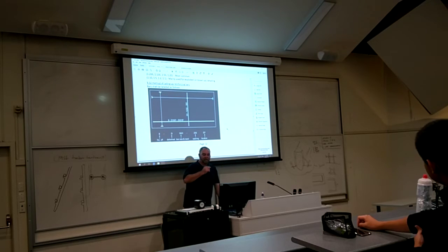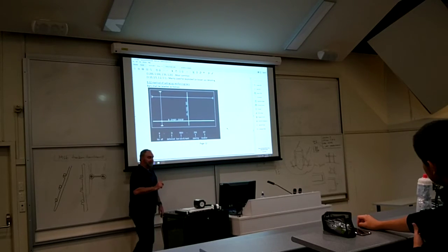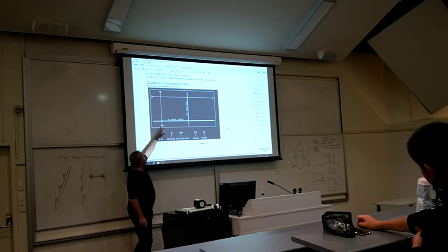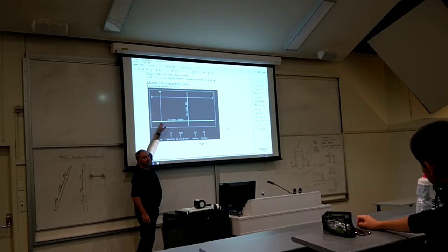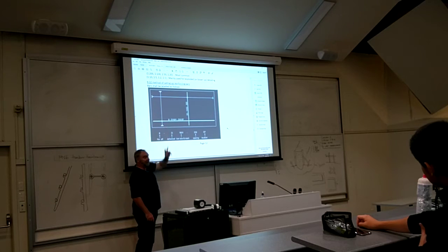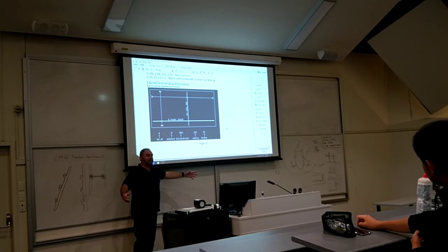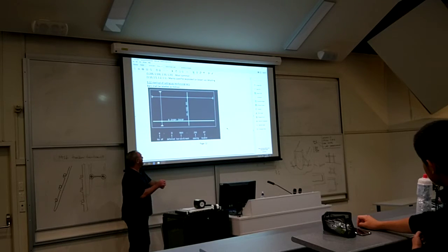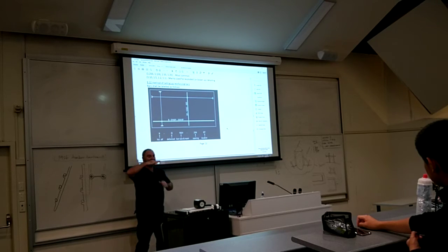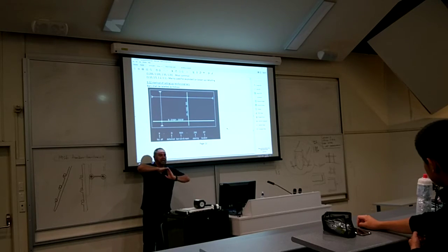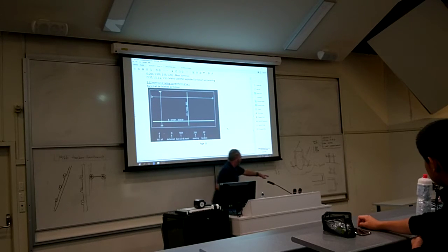Now, what I haven't said, but I will say, is that it is always an open circle, about 2 times the diameter of the bar, approximately. Not 100 times, and not the same size, because you won't see it. Alright? So let's call it 2 times. What I don't want to see is that filled in as a donut. Because if it's a donut, that means the bar goes along and comes down and you're looking down on top of it. So one of your bars curves at the end.